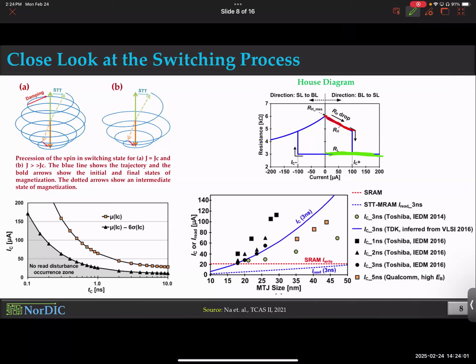Yes, it is high, but it's not constant. It's changing. Depending on which current you use to read it, it is going to change. There will be non-linearity. Similarly, for the parallel, it's not really changing that much, but depending on the MTJ structure, it can have non-linearity as well. Maybe for this particular MTJ that we are looking at for this paper, it didn't change much, but other MTJs will change. But it's safe to assume that both resistances will be a function of the applied current or voltage. Now, what is going on here?